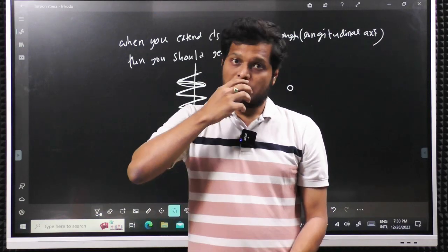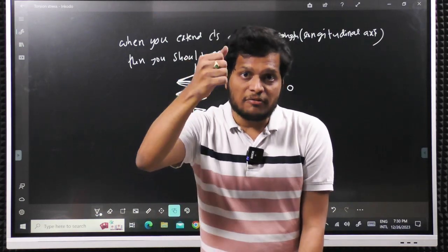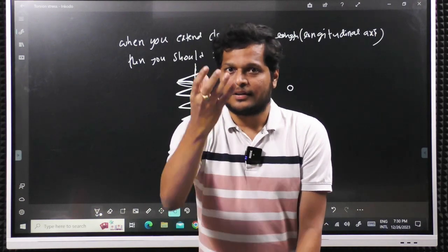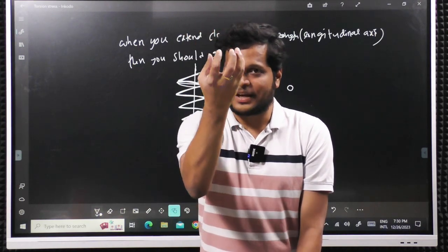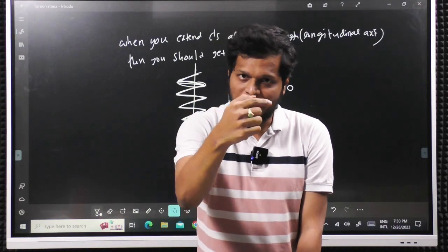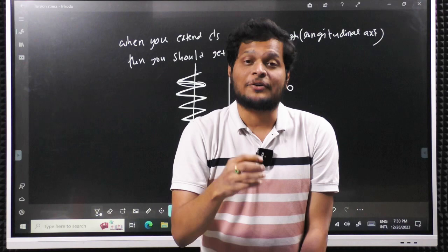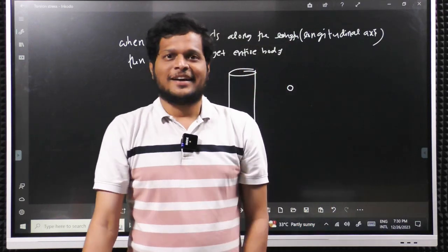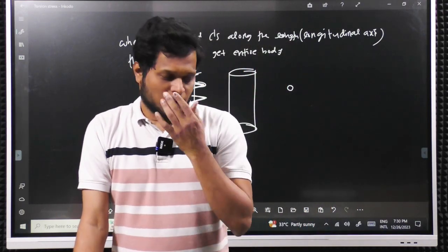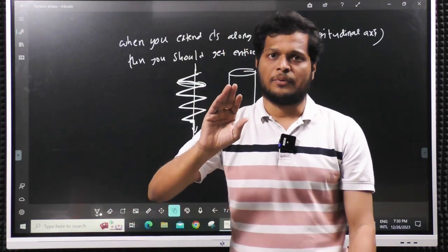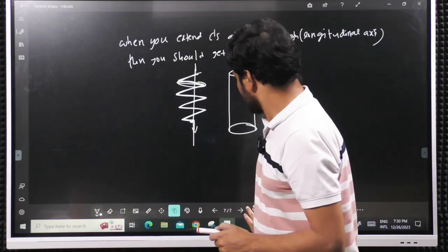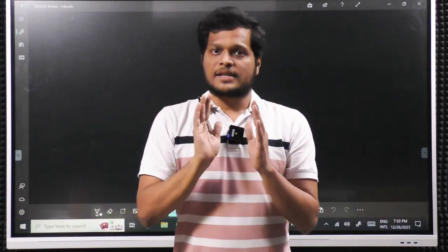Okay, so actually the twist is giving you the axial pull. The entire spring is not moving axially. The entire spring is twisting and that combined twist is shown axially. Okay, that is what happens in helical spring. So I hope now you understood how to identify the torsional axis and what is exactly torsion.